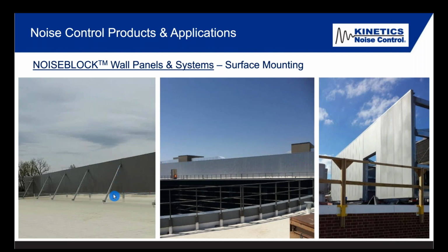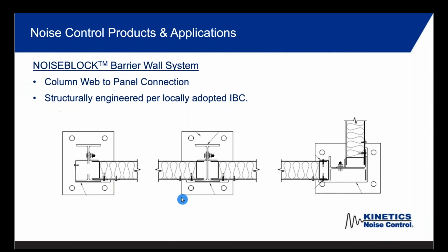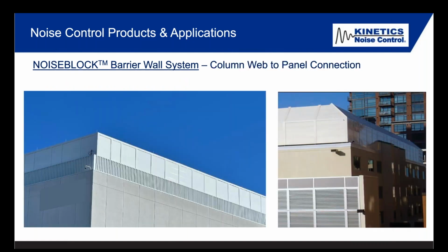Very nice. Sometimes you see knee braces, we cut around them. Sometimes they don't need knee braces, they're freestanding. These walls can be very, very long. Another option is where Kinetics is doing the structural steel altogether, and we're designing everything from base plate upward. We're supplying the steel, manufacturing, design, and all the acoustic panels, access doors, and everything, all designed per local IBC.